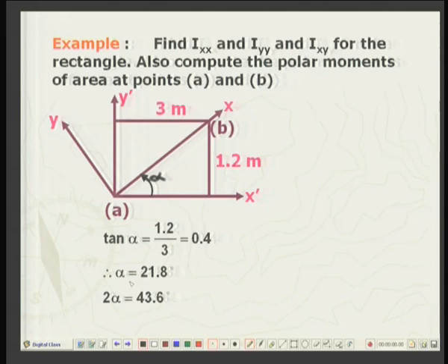Well, if I have an axis passing through the centroid of the area, that is through the center of this diagonal, this you can say is half the width and half the base. So, this is the centroid of this rectangle. We will first find out the second moments of area about these dotted axes, and then by parallel axis theorem we can shift these to the x dash axis and y dash axis.